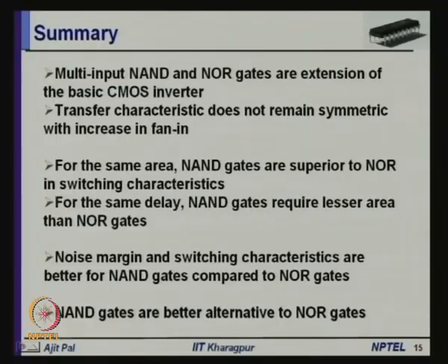We have discussed how multi-input NAND and NOR gates can be realized by extending the basic concept of an inverter by adding more and more transistors as the fan in increases. And we have seen the transfer characteristics do not remain symmetric with fan in. So, the transfer characteristic is affected by the fan in, that we have discussed in detail.